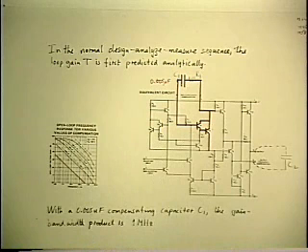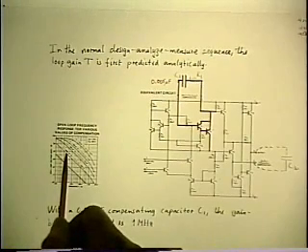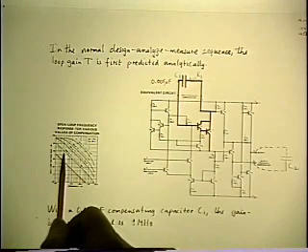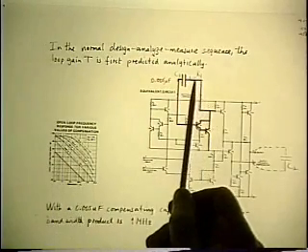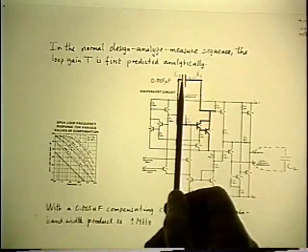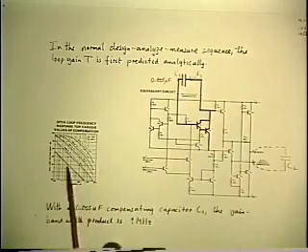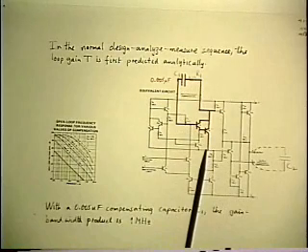Now, the third pole showed up at 22 kilohertz, which is on this diagram down here somewhere. Now, this asymptote in the data sheet did not show a pole at 22 kilohertz. Why not? Because putting this resistor there puts a 0 in the response together with this capacitor, and, surprise, 5,000 picofarads and the specified 1.5 K gives you a corner frequency at 22 kilohertz.